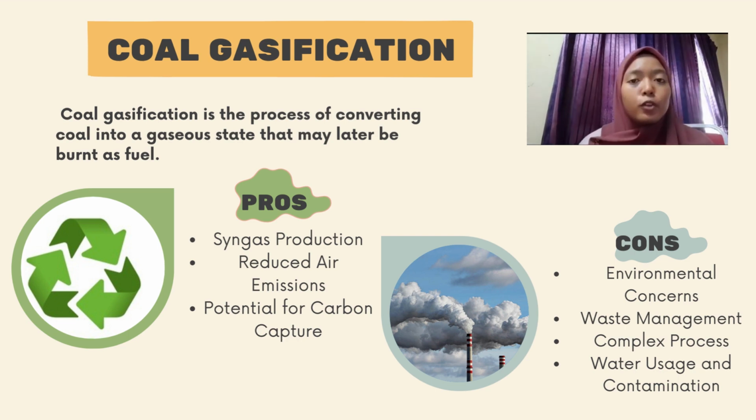Firstly, the pro of co-gasification is the production of synthesis gas. Co-gasification allows for the production of synthesis gas, syngas, which is a versatile fuel. Syngas can be further processed to produce valuable chemicals and fuels, which include a variety of products such as hydrogen, methanol, ammonia, synthetic natural gas, and liquid fuels.